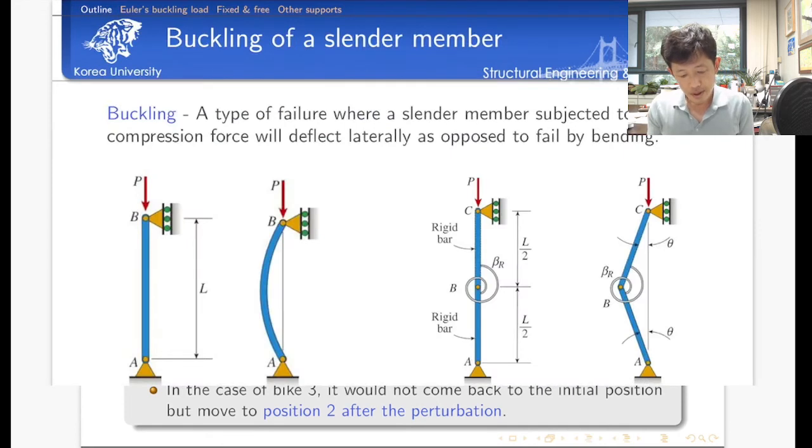Here we'd like to talk about equilibrium using the famous problem, the so-called Euler problem. Euler discussed the stability or the buckling conditions for this simply supported column. So we have a hinge here, and then I have a beam column, and I have a roller. We consider the compressive force here.